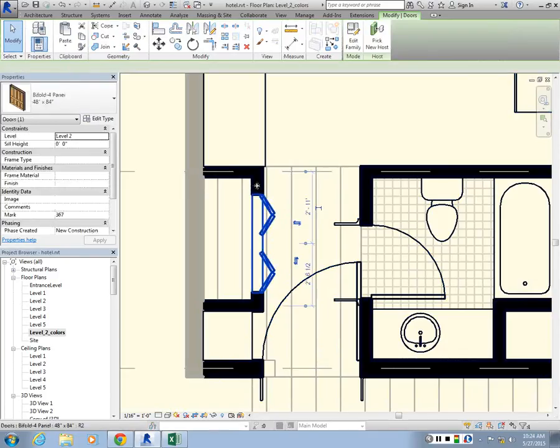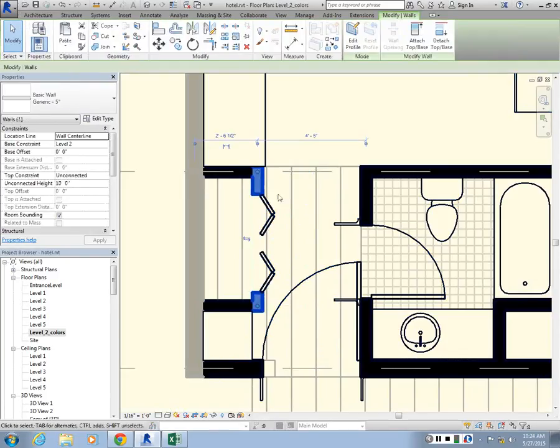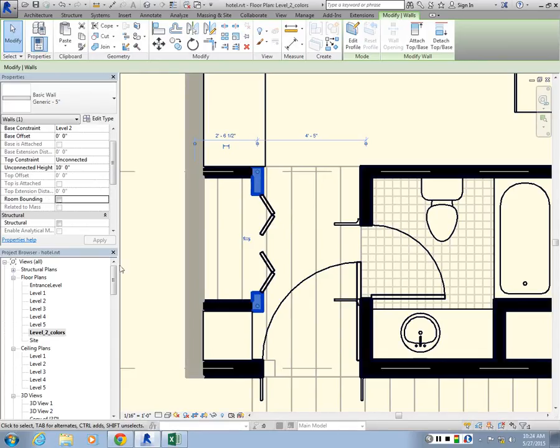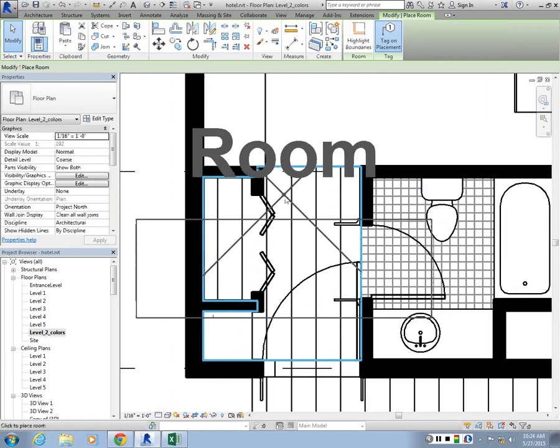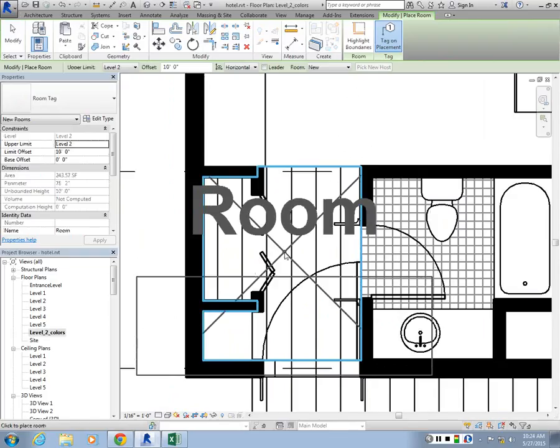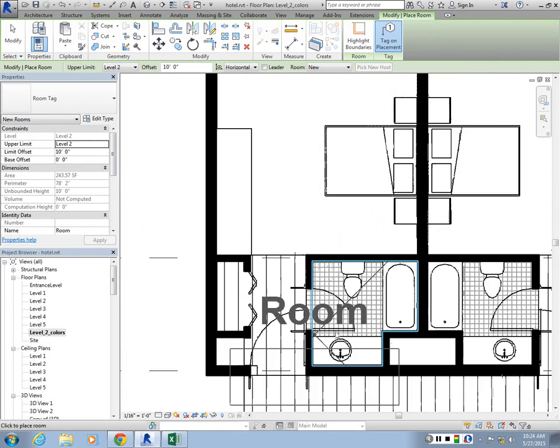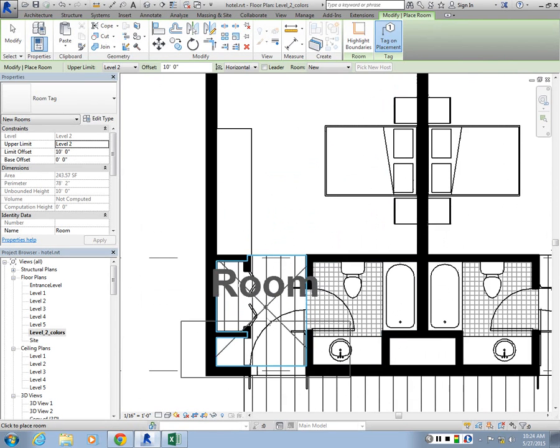You can select this wall under the group and turn off the room bounding option. So it wouldn't basically define the room boundary anymore. So if I take that out and finish, now if I come back to my room and try to select that area, it will basically now include part of the closet space as well for the room. Okay, so now I can actually create 3 separate rooms here.